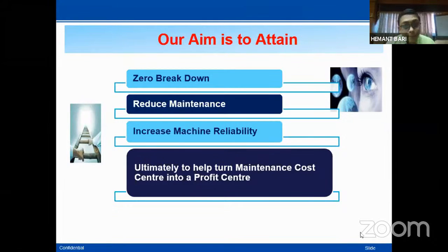My motor bearing damage, my pump bearing damage, my coupling bush damage, coupling foundation bolts deteriorated, and due to excessive vibration the pipes also damaged. It will cost you 5 lakh rupees man and material cost, and 6 days your machine is unavailable. So which maintenance you will prefer?